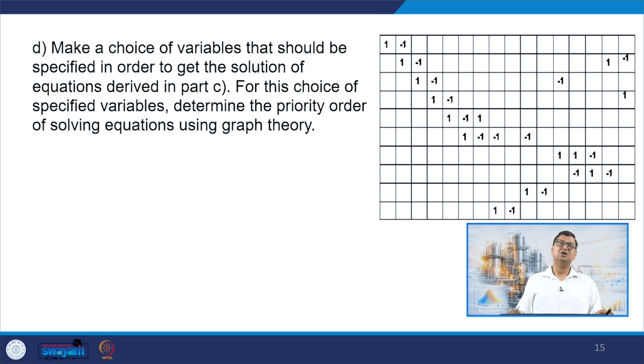So by proper choice of variables, we can reduce the graph to something that is not having cyclical nets at all. For every cyclical net, we can choose one of the variables as input so that the cyclical net is broken, and then my decomposition becomes quite straightforward.